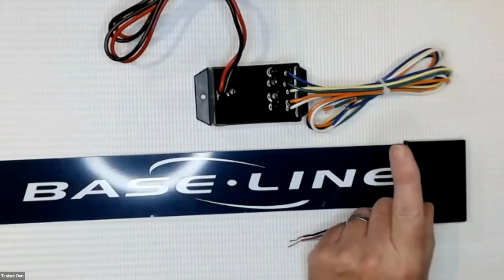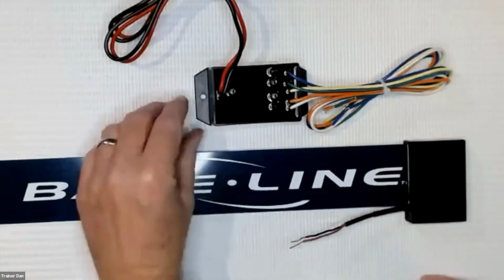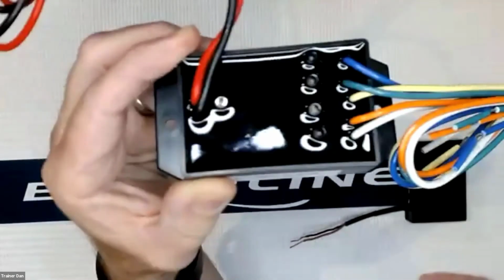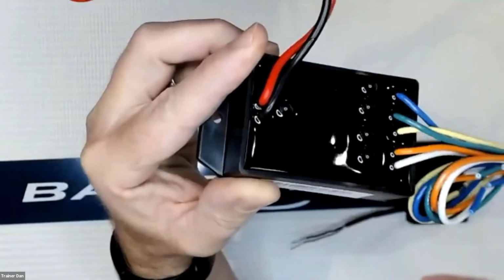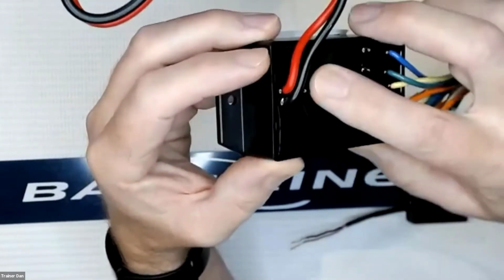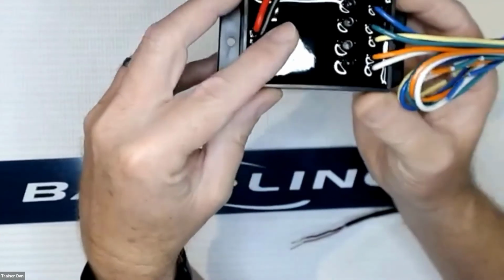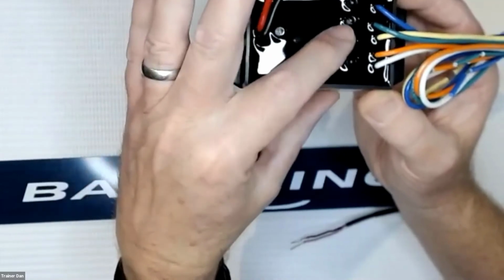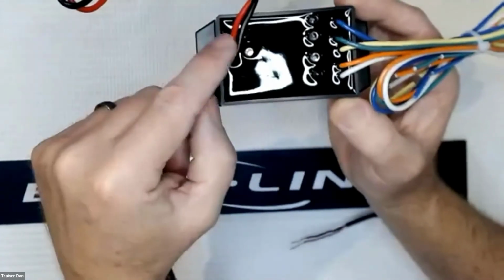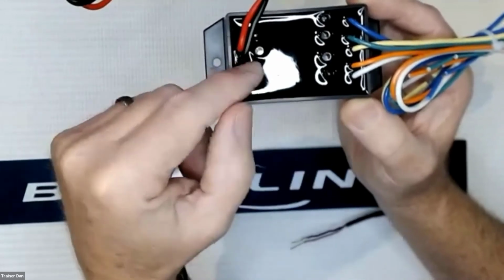So you were pointing at specific places on that decoder, right? What do we provide on the decoder that can help us troubleshoot? Let's bring that a little closer. There are actually 5 LEDs. I've got 4 LEDs here on the solenoid side, and 1 on the 2-wire side. There's what we call a blink test you can do. It would blink and tell me the 2-wire is working. Or when I test or activate this zone, the particular light will light up. So I could find out if I have a problem on the 2-wire side, or on the solenoid side, just from the lights.